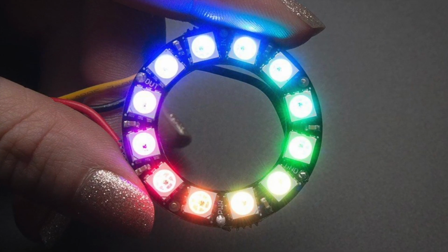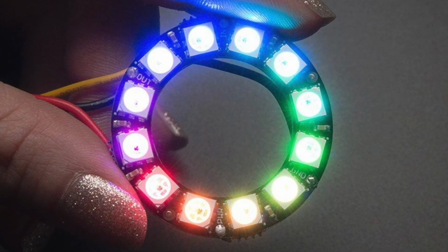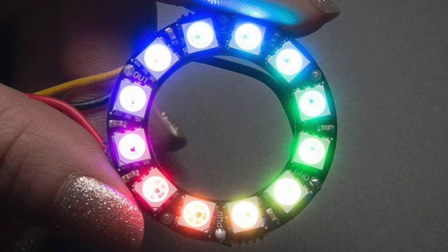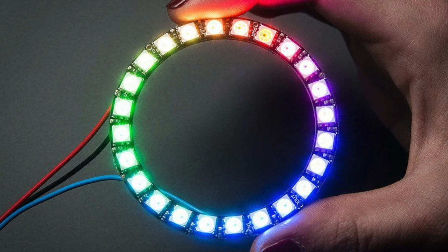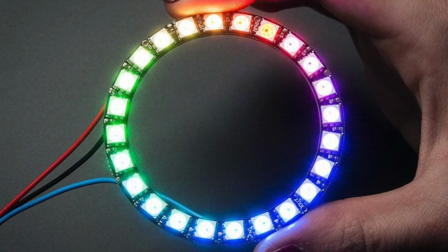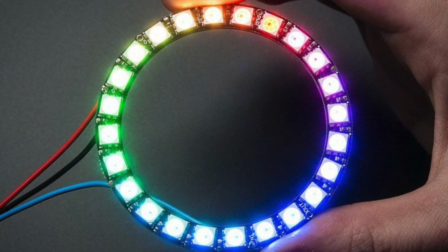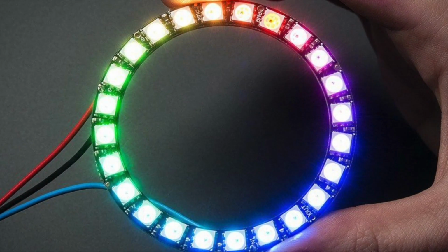LED rings. These come in sizes from about 12 LEDs up to 60. The larger rings require 2 power injections. We'll talk about those later. The smallest can be powered off an Arduino as is. These look cool as they are, but they're also fun to embed inside round objects. They can make cool eyes if you install them in pairs and are careful with the programming.